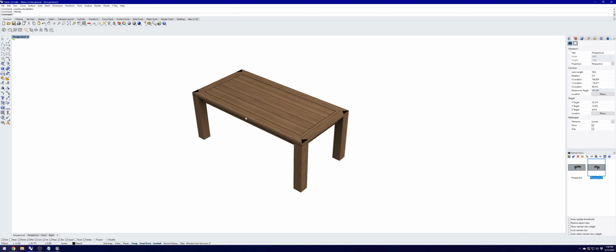And if you can't see your texture when you're editing your UV map, I should add that you're going to want to change your viewport render type to rendered. Typically I think it's unshaded. Then you're going to be able to see your actual texture on your surface.